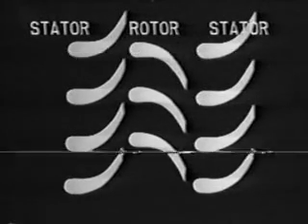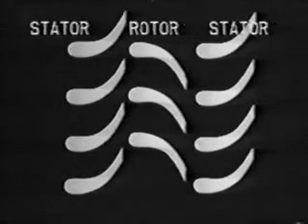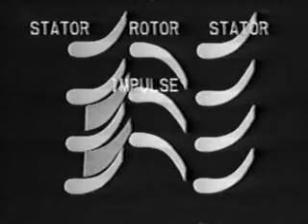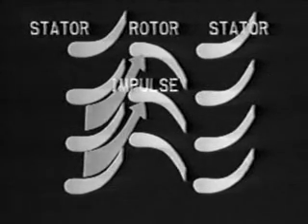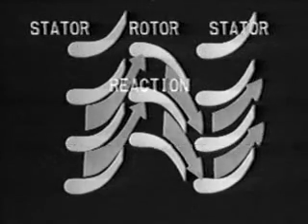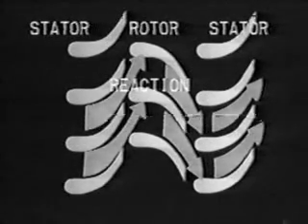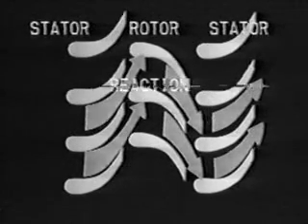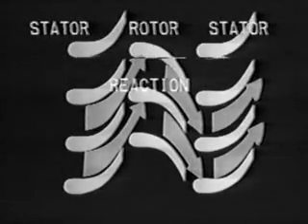This high-velocity air is used in 2 ways in turning the rotor blades. The first is by impulse. Air is directed towards the blades, forcing them to turn away from the nozzle, turning the turbine shaft. The second is by reaction. High-velocity air expands as it passes through the rotor blades, pushing the blades in an opposite direction, again turning the